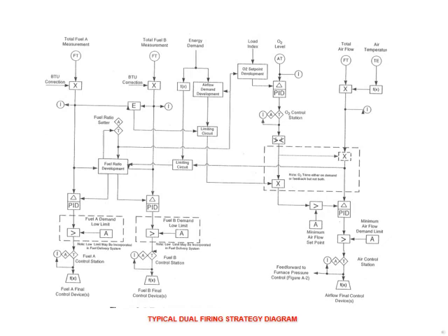Okay, a metering type control strategy for a boiler capable of dual fuel firing simultaneously has to account for the total furnace heat input and different fuel and air ratios. The basic strategy of the boiler energy demand, establishing the total fuel demand to the boiler and the fuel to air ratio on a boiler basis, is to be satisfied.